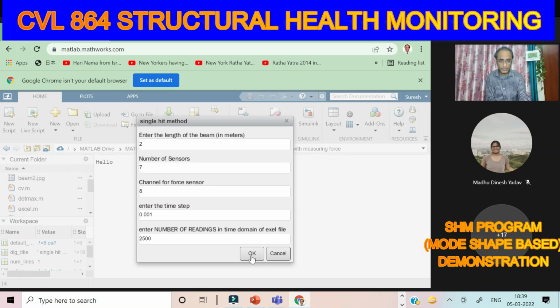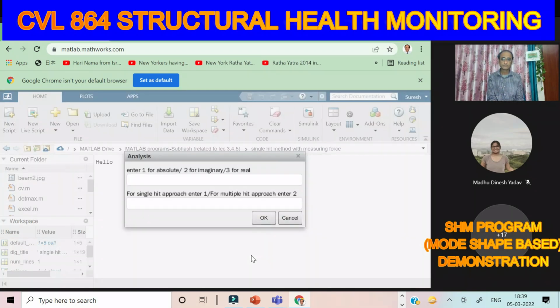Okay, so I'm pressing OK. Now it gives us the option of what we want to use: the absolute part, the imaginary part, or the real part. We have seen that the absolute part is very good for identifying the peaks, the natural frequencies. You can in fact run it for absolute also, but I am running it directly for the real part. You can also run it for the imaginary part, or you can first run for the absolute, so that you get the peaks.